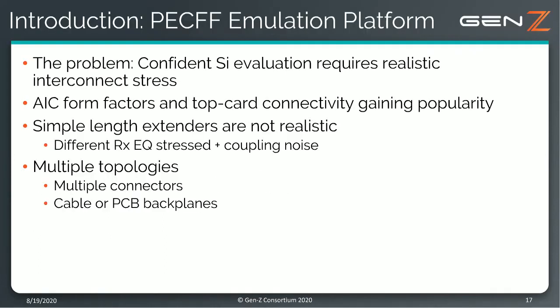So let's talk about the emulation platform, introduce it, and talk about the problem that it's trying to solve. The problem that we were thinking about solving here is the silicon and PHY designer or the OEM platform designer that wants to test the PECFF style interconnect and is looking for a way to do it. We know these add-in card and ganged add-in card form factors are gaining popularity, as Matt just cited. They're particular electrically in their number of connectors, their PCB lengths, and the amount of noise that you face from a signal integrity point of view.